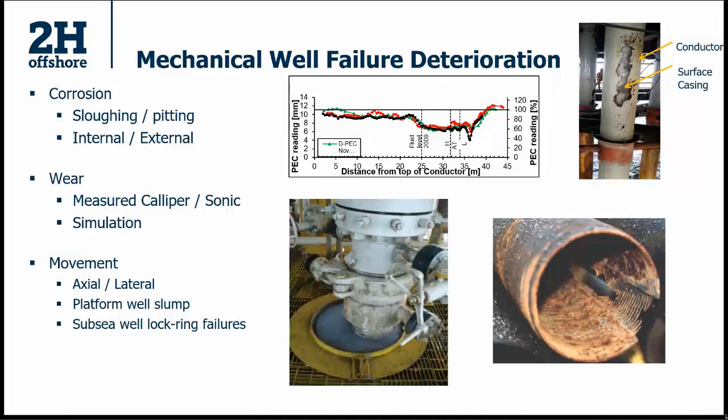So modeling the material loss, it's different if it's from the inside of the pipe or the outside of the pipe, so that can be challenging to model. Drill through wear, that's that bottom right picture there. You can see that drill through wear, that wear groove is actually cut right through into the thread form there.